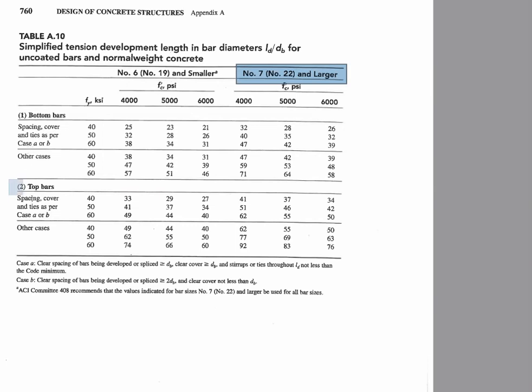And the reason, by the way, you might have top bars on a footing is that you could consider having a mat foundation where you have multiple columns coming down onto a given pad and soil pressure acting upward everywhere. And what's going to happen is your foundation is actually going to go through kind of a wave type response to that, a static wave where it just gets loaded down at the column location, but in between them actually goes up and then goes down for the next one.